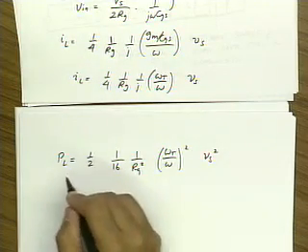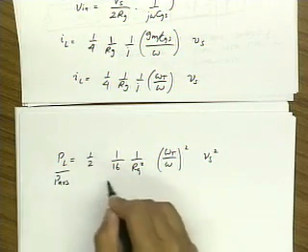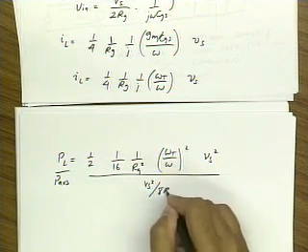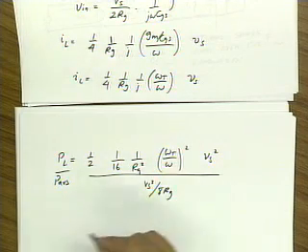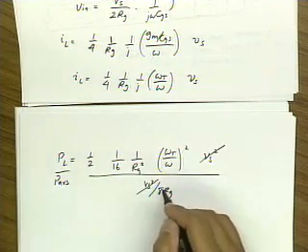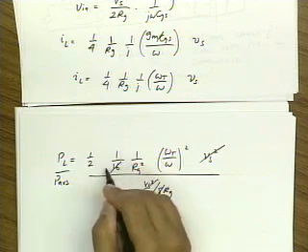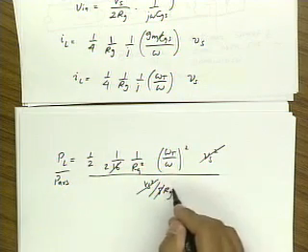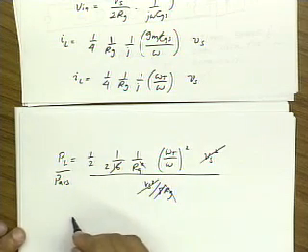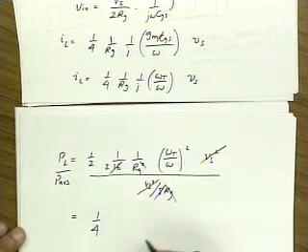And if I now divide this by power available from the source, that's Vs squared over 8Rg, the Vs squared cancels out. This 8 cancels out with this, and I get a factor of 2 here. This Rg cancels out with this Rg. And so my final expression looks like 1/4.